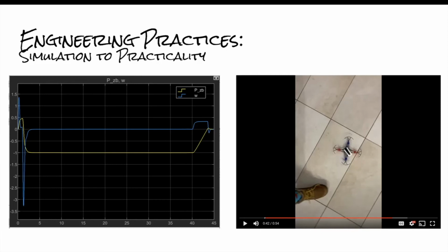Additionally, there are issues with debiasing that you need to take into account. The elevator may not always be perfect. You may not have perfect motors. We ended up actually having to debias our second motor by 30 hertz, which was a huge difference from our simulation, which greatly affected our measurements for a long time, as well as having to change assumptions that we might have in our simulation, like our CT value.